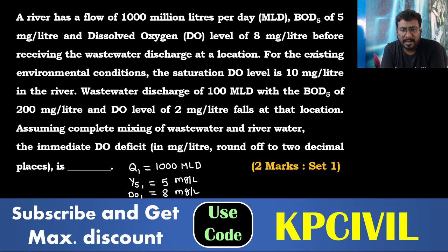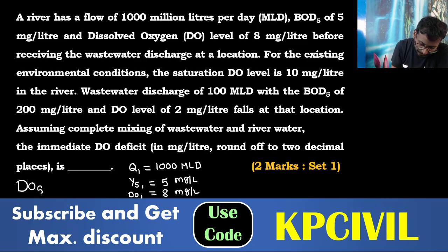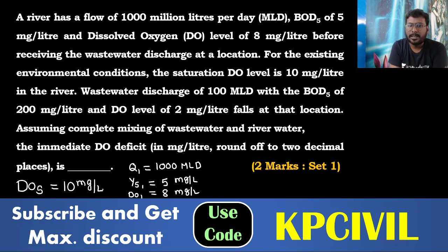For the existing environmental condition, the saturation DO level is 10. DOS, saturated DO, 10 mg per liter. Wastewater discharge of 100 MLD with BOD 5 of 200.